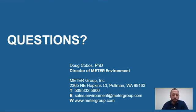So the effect of organic matter, what that is typically going to do in a clay soil is, if you have more organic matter, you're probably going to end up with more soil structure and better aggregate stability. And so what that does is it changes the water potential at a given water content, right? So that moisture characteristic curve can change, especially in the wet end, and give you all kinds of benefits. It'll give you more water holding capacity. It'll give you better aeration. It'll give you better infiltration rate in those clay soils where your hydraulic conductivities may be typically pretty low, but it won't directly change the water potential, because it's nature that changes the water potential all the way from really wet to really dry.